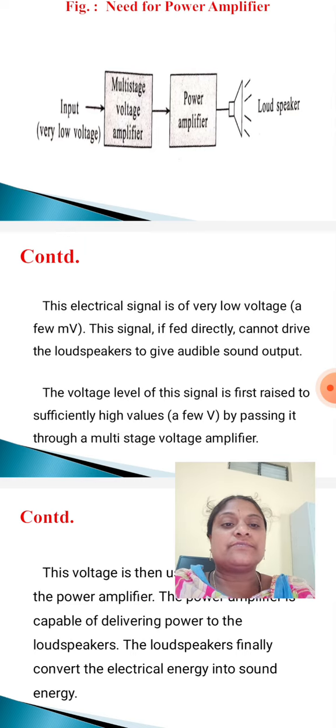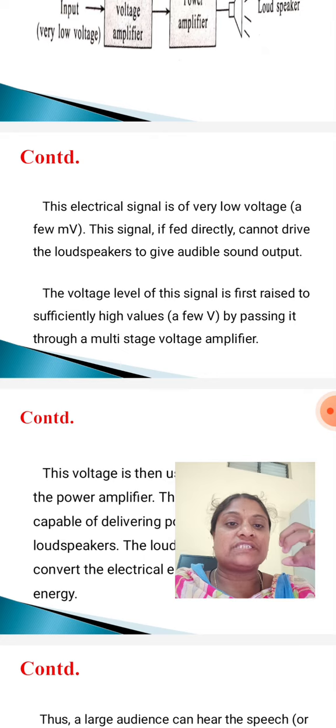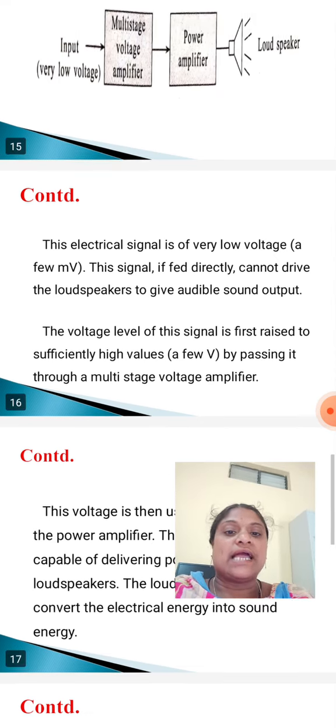I repeat this point again. This electrical signal is a very low voltage signal. The voltage is a few millivolts. This signal, if fed directly, cannot drive the loudspeakers to give audible sound output. The voltage level of this signal is first raised to sufficiently high values, a few volts, by passing it through a multi-stage voltage amplifier.